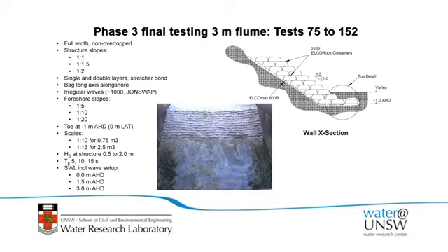If you're into water levels, you'll know the open coast water level on the Australian east coast is about your 1 in 100 year level, 1.5 metres AHD, but realise we're inside the surf zone, so we have wave setup on top of that. This wave setup level inside the surf zone pretty much represents about the highest wave setup level you'll get anywhere on the east coast of Australia. You could theoretically get a 10 metre wave, which would give you 1.5 metres wave setup on top of your 1.5 metre water level. So that's 3 metre AHD water levels, pretty much an upper limit for anywhere open coast, east coast Australia. Wave run up still goes above that as well.